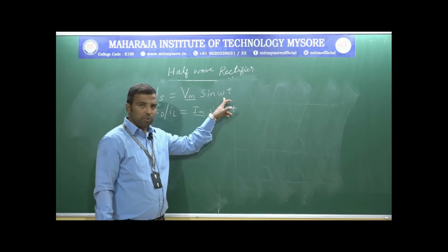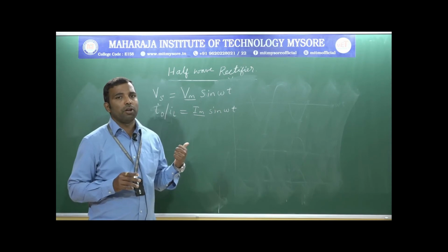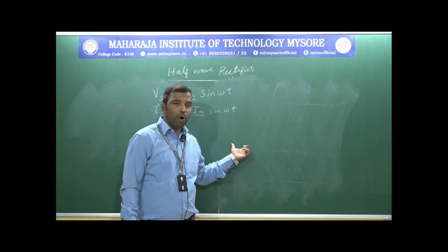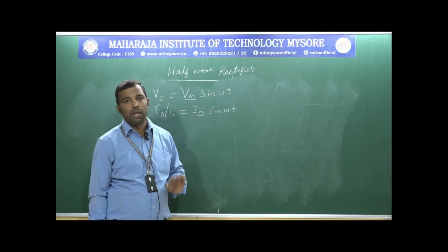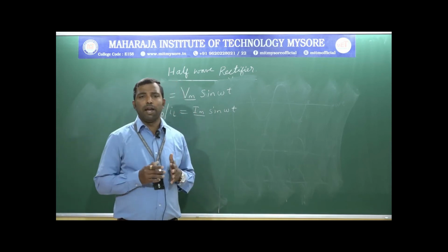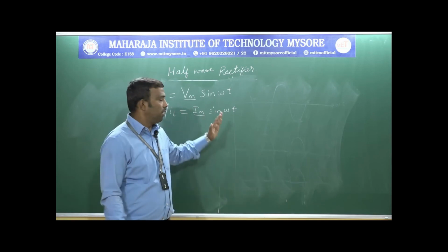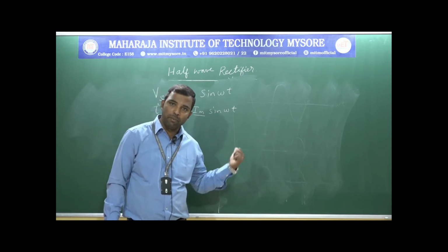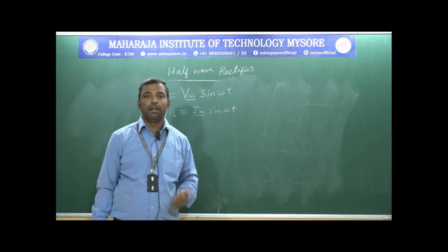We write this as a sine function because it is a continuously varying AC function. The rectification is not 100%. Therefore, we can say that the rectified output is not pure DC, it is pulsating DC. Pulsating DC means the DC value of the rectifier output also has some AC value. Ripple means the AC component which is not required in the rectifier output, but is present in the rectified output, which is called pulsating DC.